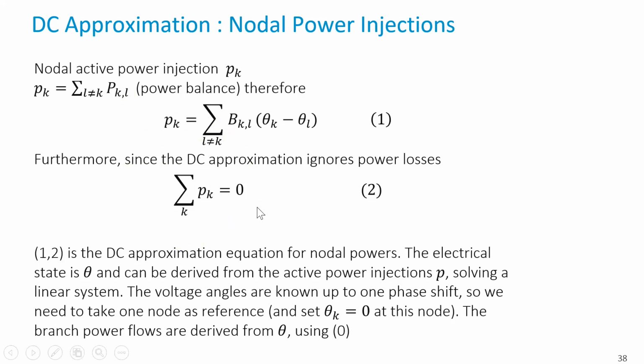So when we use the DC approximation to close markets at continental level of Europe, for example, we first do a DC approximation, we allocate all the power flows, but then we must do an allocation of losses, because when we do the real stuff, there will be a few % of losses. So this is typically requiring an additional step after the optimization based on DC approximation.